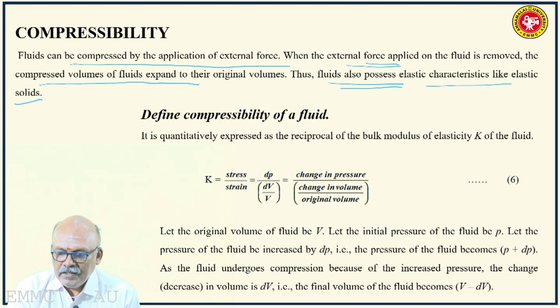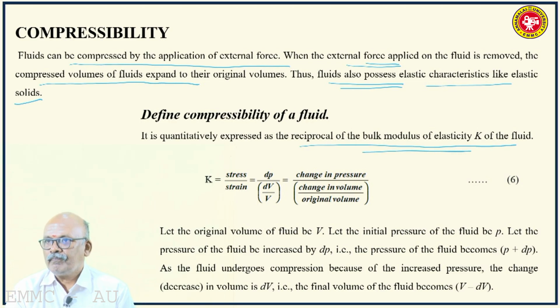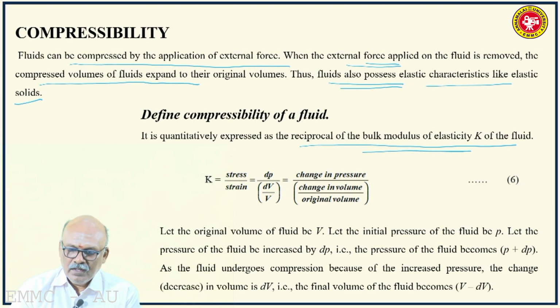Now compressibility is nothing but the reciprocal of the bulk modulus of elasticity of the fluid. So how is bulk modulus defined? Bulk modulus is given the notation capital K. It is stress divided by strain.